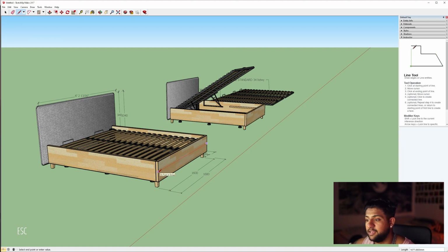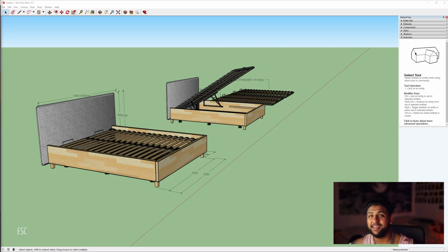Now, as you'll notice, as you draw lines, they will snap to green, blue, and red. These are because they'll snap in the X, Y, and Z axes, and it's a really good way to tell if your line is straight. So I've done a line across here and it says 1677 millimeters. Now on the floor it says 1600, so this is close enough. It's most likely correct.